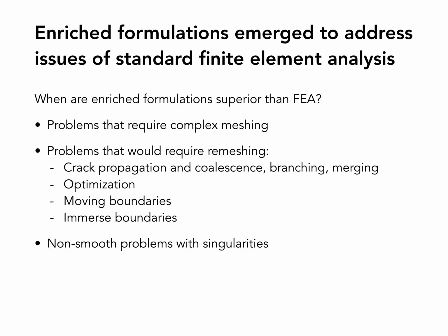We use polynomials in standard FEM, but you can actually add to the formulation anything you want. If you add a singular function to the formulation, then Galerkin is going to tell you whether whatever you throw into the method is really improving the approximation, because it's going to reduce the error. So you can pretty much throw in any function you want. If you know something about the solution of your problem, you can throw in that function, and if it is really useful, then Galerkin is going to tell you because the error is going to be reduced.